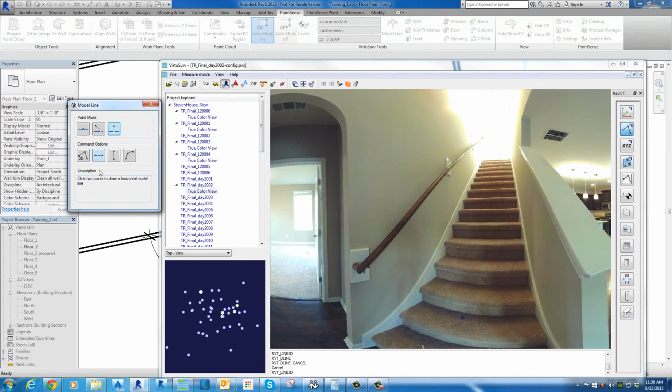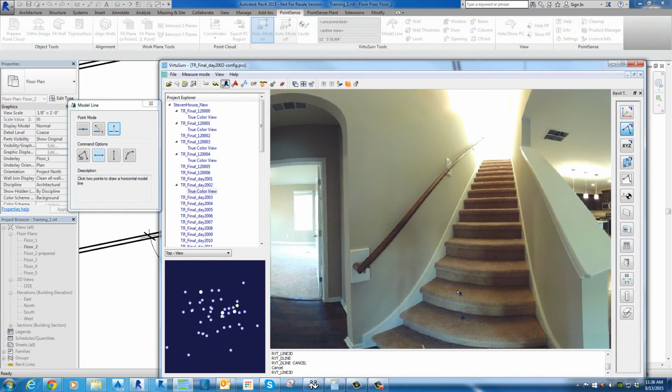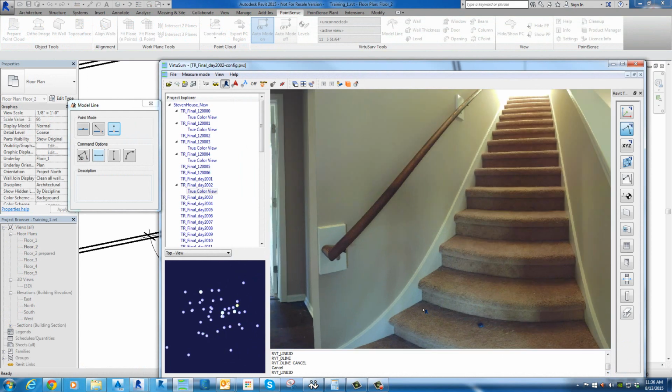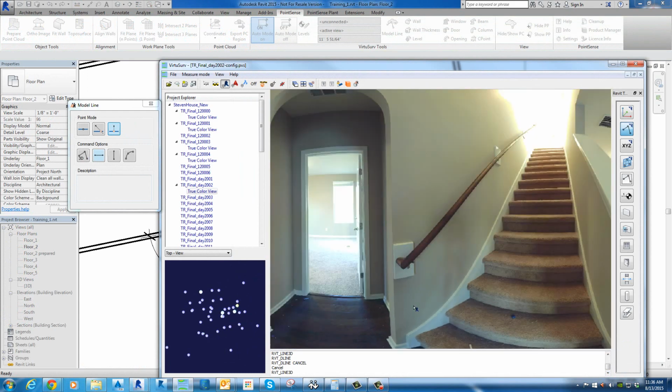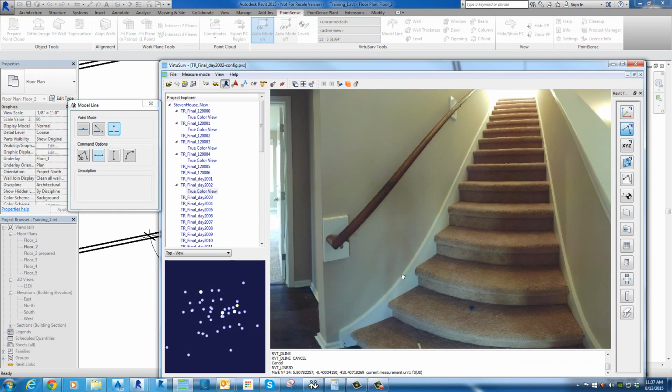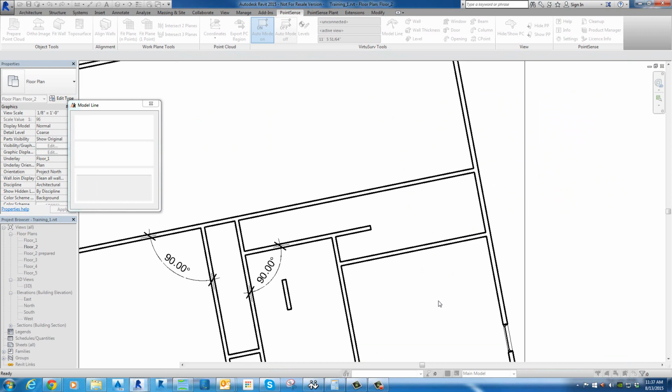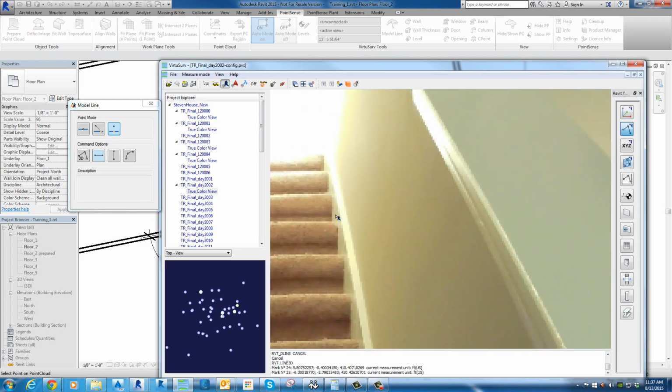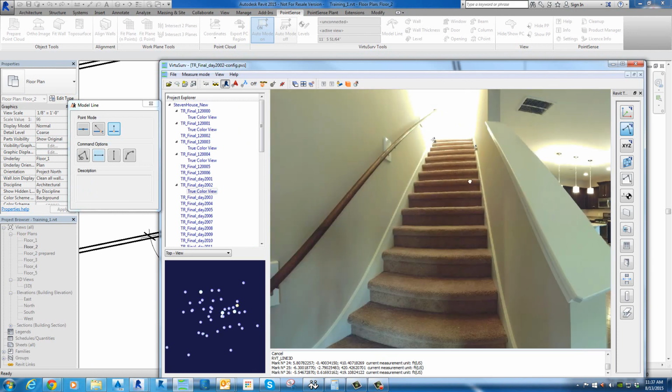Creating stairs and irregular objects, you have the option to just lay out modeling lines. In this case, we're going to lay out horizontal modeling lines for the boundary of the stairs and for the risers. And to do that, it's really simple. I find it much easier to click in the high-res image view in VirtuServe to send our line work over to Revit.